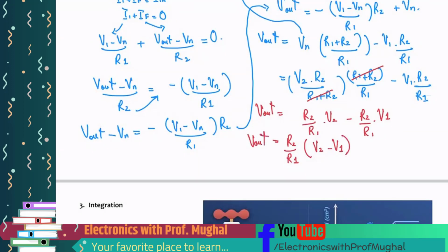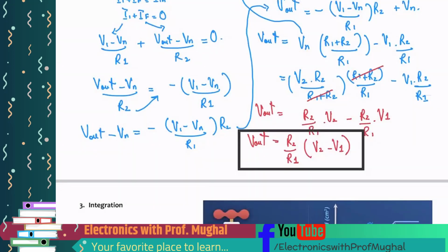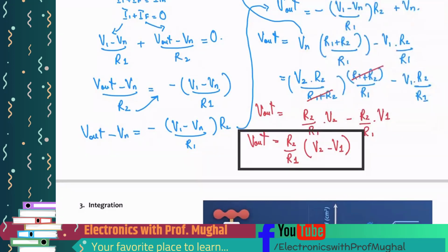And once I have this equation, if I am only interested in getting a difference of the two input signals, I don't want to magnify it. What can I do to this equation right here? Make R1 and R2 equal. Yes, absolutely. If you are not interested in the gain, you want to get the difference.